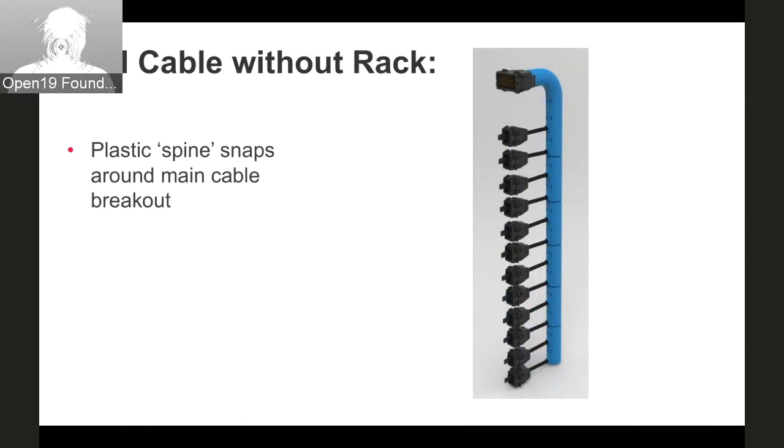This cable, since it's doing snap and a backplane function, has a really, really low chance of failing. However, if a failure does happen, and failures always can happen, unfortunately in this configuration you have to replace the whole harness or give up on a slot. Those are the two things that you can do. There is no way to replace a single connector on the snap because it's completely tied into the spine. Okay?